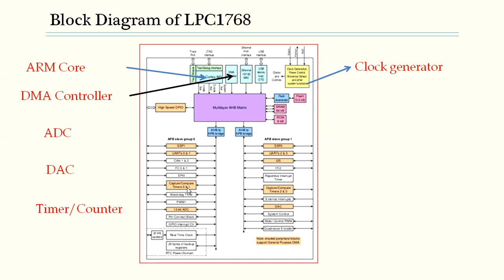The timer counter is mainly designated to count the cycles of the system, which is derived from the clock, or it could be an externally supplied clock. It can optionally generate interrupts, generate timed DMA requests, or perform other functions at specific time values.